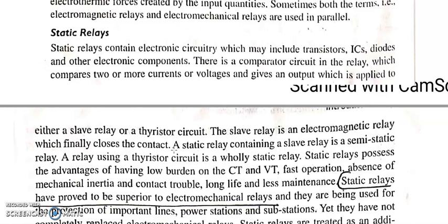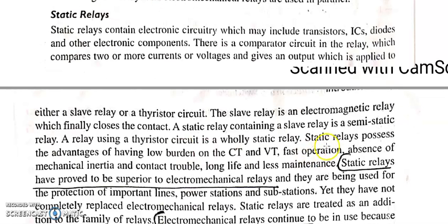Here we have some advantages in the static relay. It has low burden on the CT and VT, and fast operation, as well as absence of mechanical inertia like we had in the electromechanical relay.